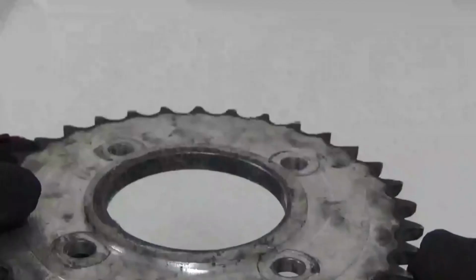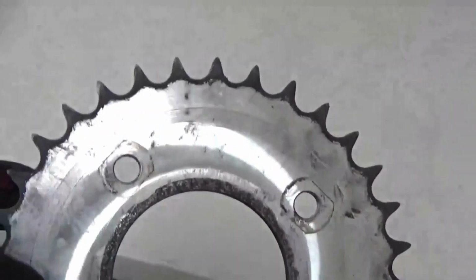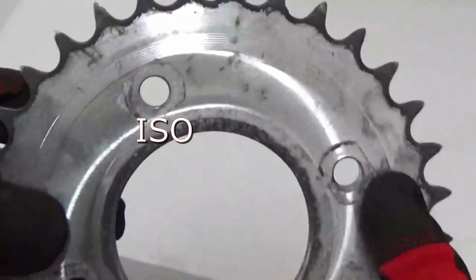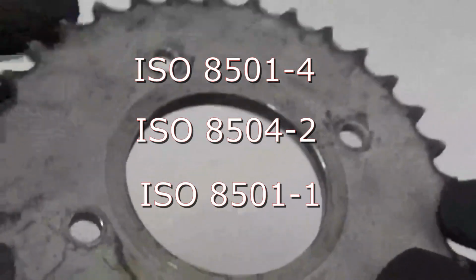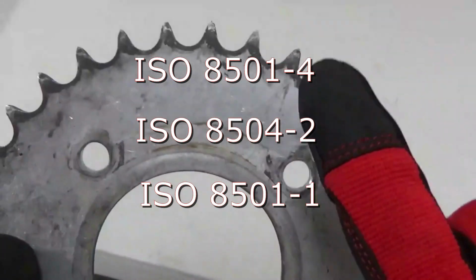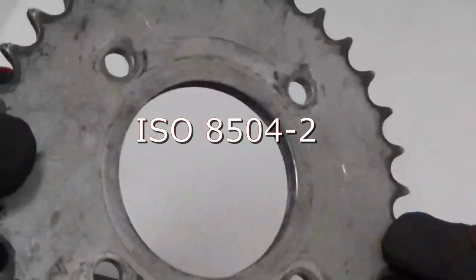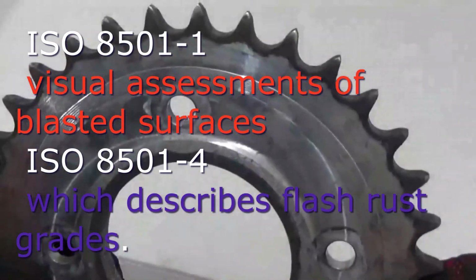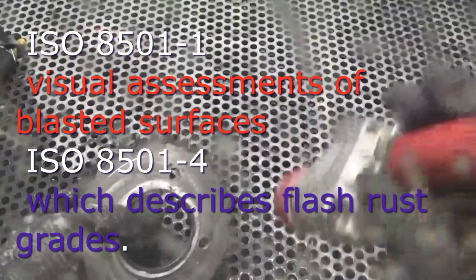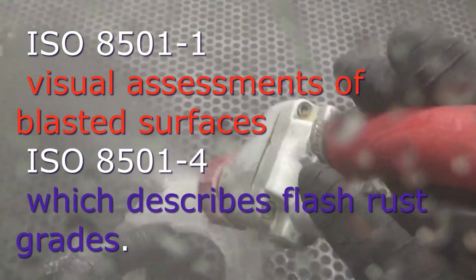Since vapor blasting is the latest blast cleaning method, it is not described. However, we can easily extrapolate vapor blasting to ISO 8504-2, ISO 8501-4 and ISO 8501-1. There is no dedicated ISO standard for determining the visible cleanness of blasted surfaces. The best method is the IP method, which introduces internal standards that combine the ISO 8501-1 visual assessment of blasted surfaces and ISO 8501-4, which describes flash rust grades.